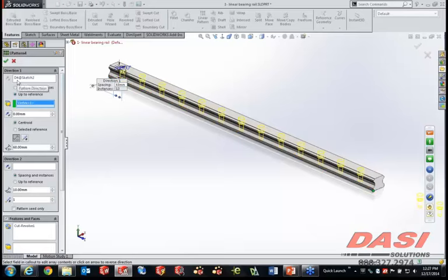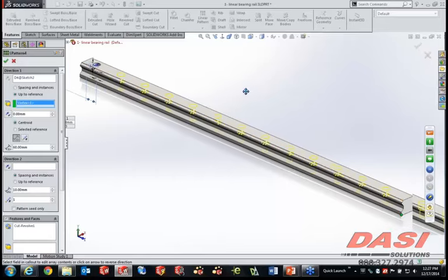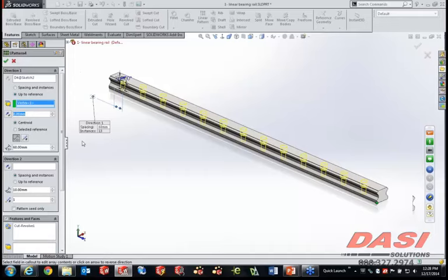On top of that, what we have also is an initial spacing. If you look over here, this is 25 millimeters off the beginning of this rail. Now 25 millimeter start is probably what we're going to want on the other end too, so we want 25 millimeters down here. And I could easily type in 25 in this offset distance box, but it's really easier or better for the system if I just make this an equation.